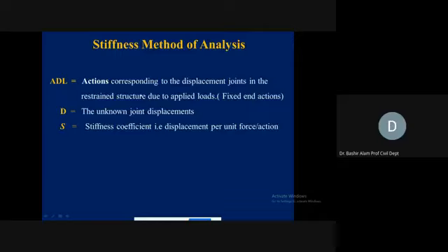Here, just for the specific case, with the help of the established equations, you will quickly find the member end actions, and quickly you will include them in the ADL matrix. Similarly, if you were using the unit load method for finding the displacement, if you remember, writing the moment equations and then the summation of the integral of capital M times small m times dx divided by EI, a lot of work was involved there. But here it will be real quick.